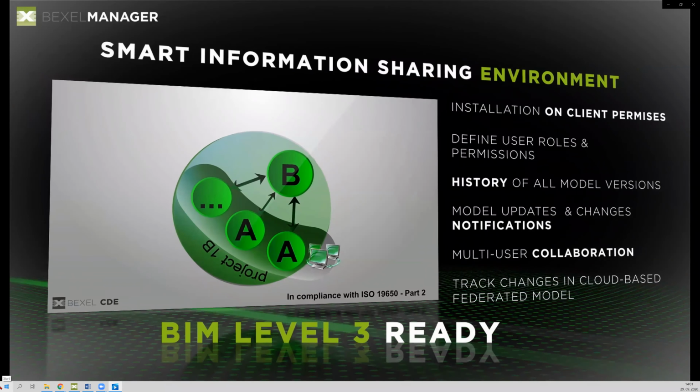That was mentioned and covered in lesson 2. If for any reason you would like to review the properties your project contains, please just click on a certain element or a group of elements of the project, and the properties palette will activate, where you can review all the properties this model contains. Also, we talked about how you can add new properties, although we highly advise you to add properties to your BIM model in the BIM authoring tool.